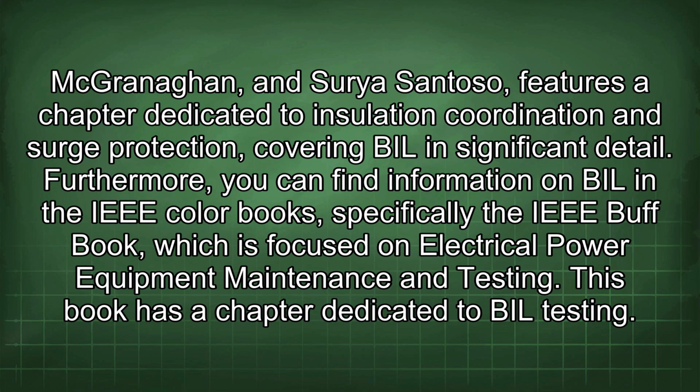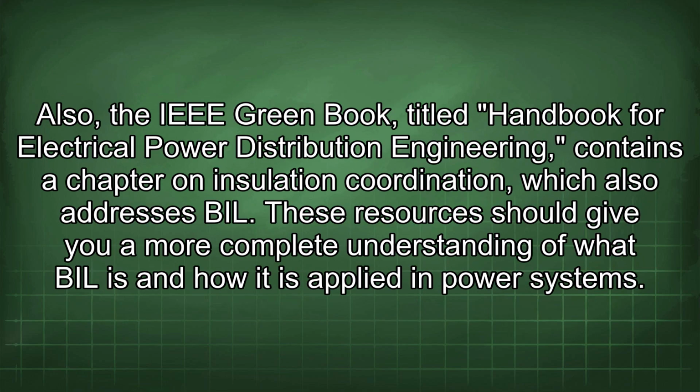Furthermore, you can find information on BIL in the IEEE color books, specifically the IEEE Buff Book, which is focused on electrical power equipment maintenance and testing. This book has a chapter dedicated to BIL testing. Also, the IEEE Green Book, titled Handbook for Electrical Power Distribution Engineering, contains a chapter on insulation coordination, which also addresses BIL. These resources should give you a more complete understanding of what BIL is and how it is applied